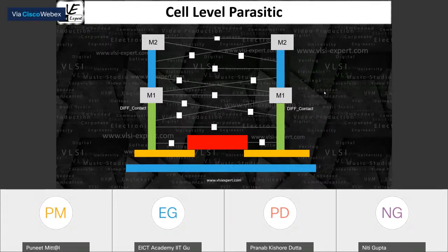Device level parasitics are fixed, or do they vary through different stages? So Harish, no. Once the placement of all the cells is done, if you are not going to change the placement, the device parasitics are almost fixed.